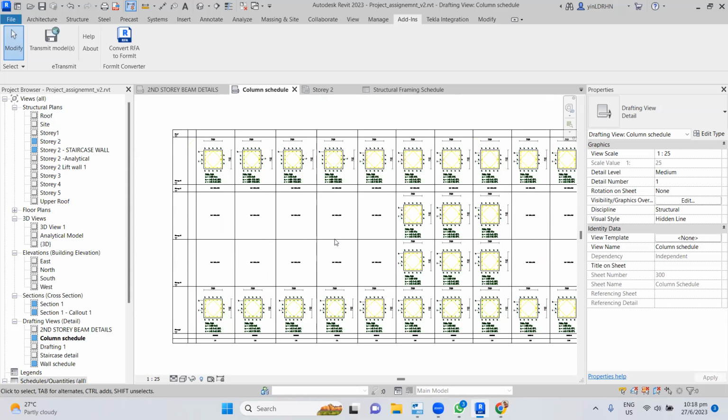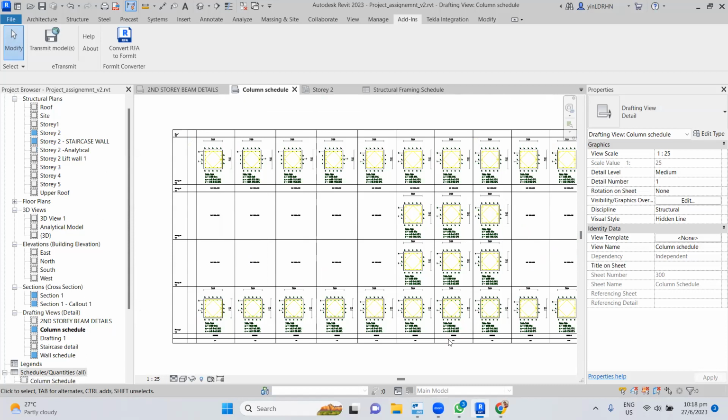Contractually, if you don't want to do it, then you can use a 2D drawing. It's easier and faster. No need for additional effort. You see how easy this one is? Just export from Tekla, do some modifications, then you can import it, and your work is done. But if you want to produce a 3D drawing, you have to draw the rebar according to your design. Then you have to draw the proper lapping and so on. You need additional work.